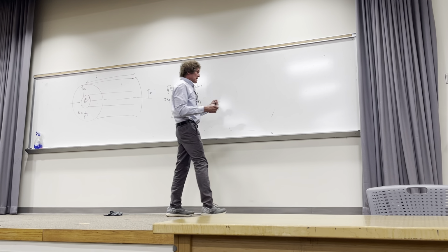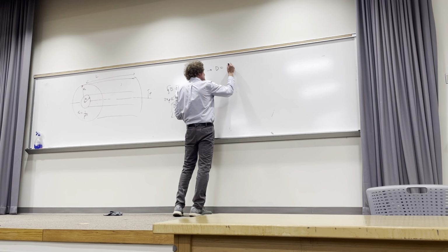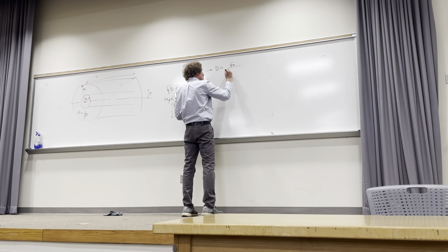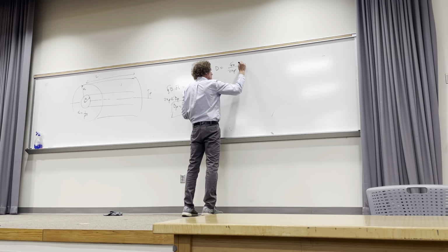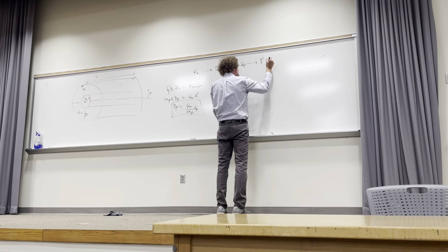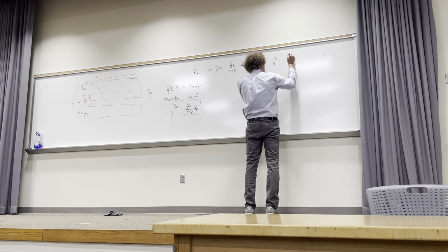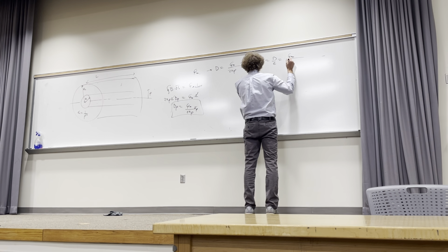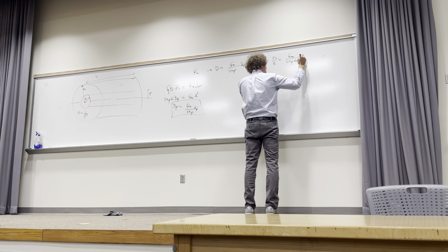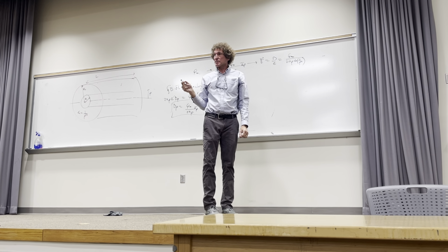We started with Q, and we get D equal to the charge per meter over 2 pi rho, a rho. Then we get E, and E is equal to D over epsilon. So I take this D, Qm over 2 pi rho, times epsilon naught, divided by 1 over rho squared, because I gave you epsilon relative as 1 over rho squared, correct, class?